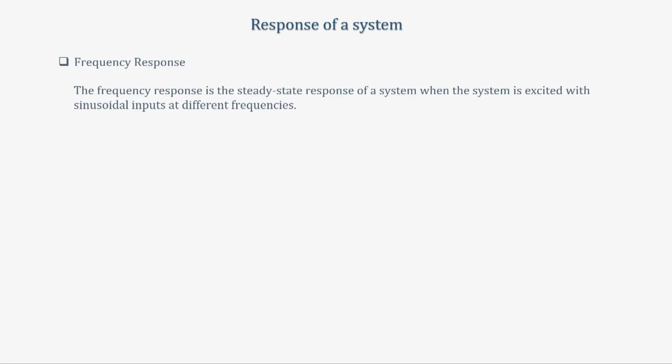Now, what is frequency response? The frequency response is the steady state response of a system when the system is excited with sinusoidal inputs at different frequencies. Okay. If you have a system, again an LTI system, and you are giving sinusoidal input to the system with different frequencies, then the output that you get is called the response of the system with respect to the frequency which you are giving as input.